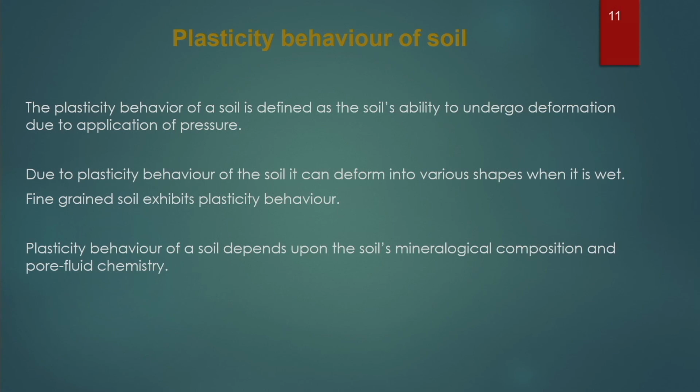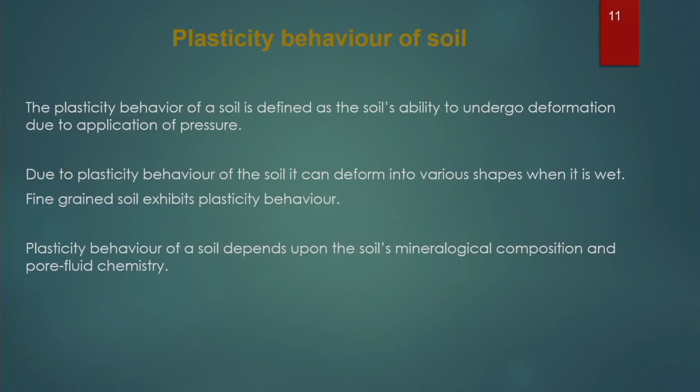Next we will discuss the plasticity behavior of the soil. Plasticity behavior of the soil is the ability of a soil to undergo deformation due to application of pressure. You might have seen some clay which we can mold into different shapes by applying some pressure. That behavior of the soil is known as plasticity. By plasticity behavior, the soil can be deformed into many shapes. Generally, the plasticity behavior of the soil depends on its mineralogical composition as well as its pore fluid chemistry.